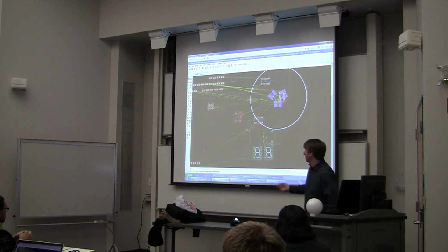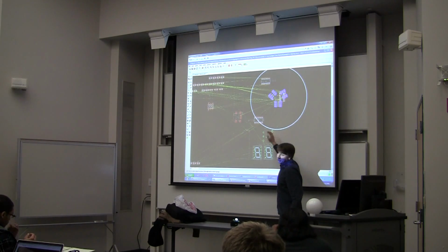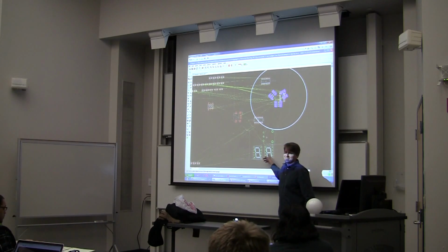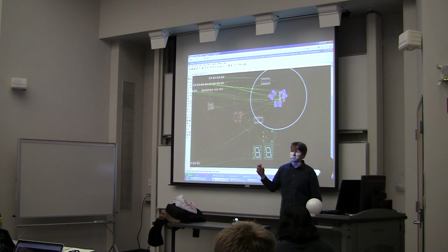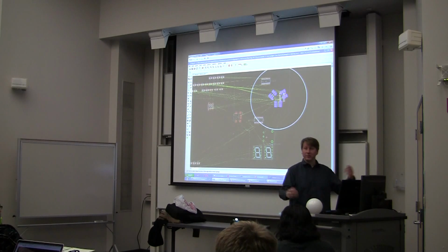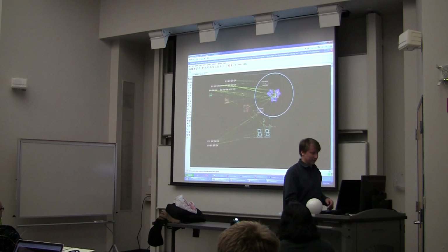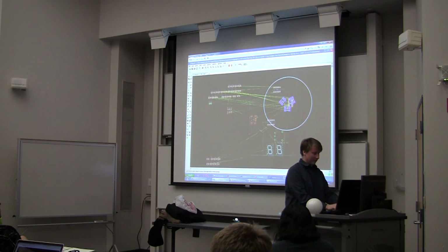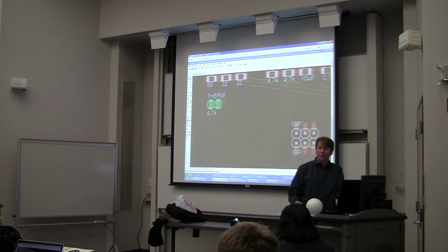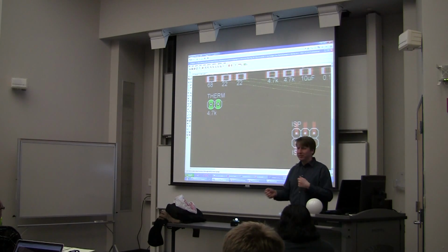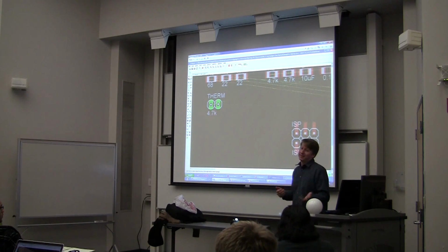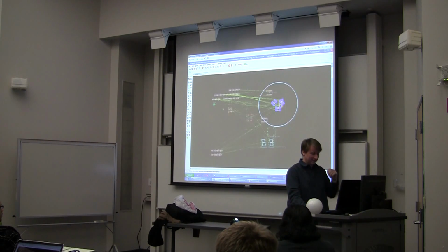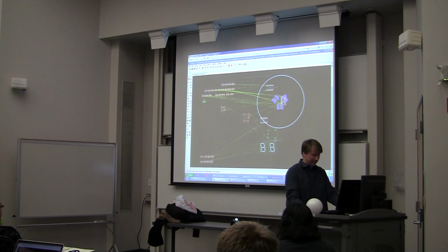In the case of the potentiometer, it wouldn't actually matter which side you soldered it into, but these things, you can't just leave them on the top and then flip them around. It just does not go. Right? You can't just flip everything around. You have to use the mirror command so that it works correctly. Whereas this thermistor, right, it has two legs. It's a resistor. Which side of the board the part is on doesn't matter. But for other parts, it generally does. So that's some fun we can do with the layout.